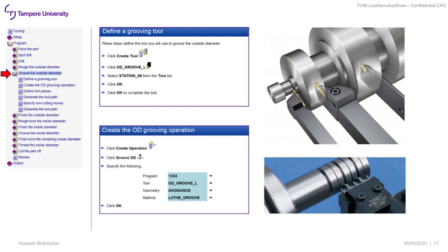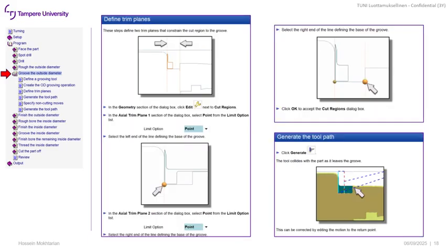The groove tools, we can have different groove tools, but anyway, if it is like a family of the groove tools, it's the one that you can see on the bottom side. If not, then these are the normal groove tools that can also be used to cut off the parts. We're going to define the groove tools, and then the geometry is avoidance, and then the rest would be just the easy operation. For the groove tools, we need to define the limit of starting and at the end, and I will show you what will happen if not. And then sometimes we also need to pay attention to the colliding of the part itself or not.